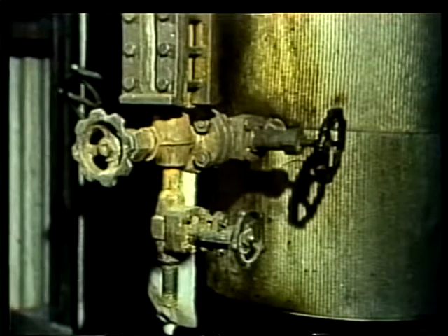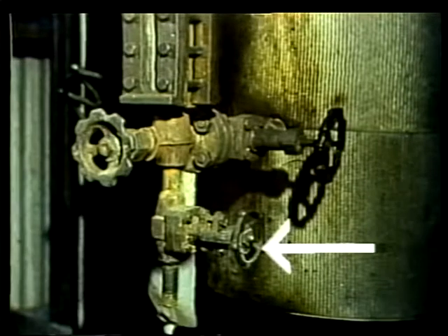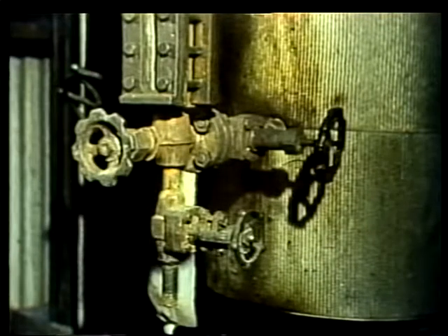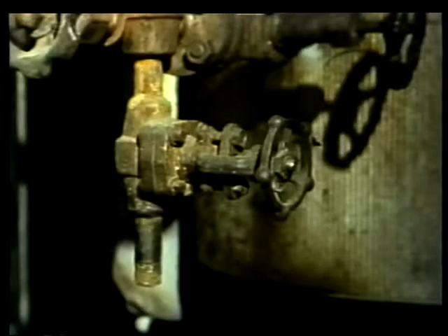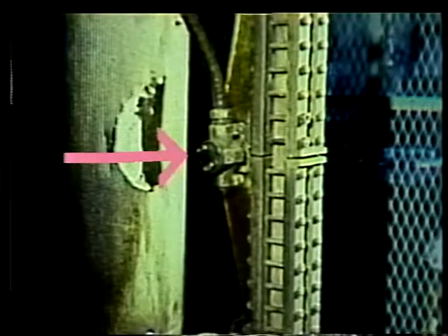Another feature on a flat glass gauge is the drain valve. It is attached to the bottom of the gauge and serves the same purpose as the petcock that is attached to the bottom of a tubular glass gauge. Both are used to drain the gauge when the rest of the plant is in normal operation. Some flat glass gauges have illuminators. That's because flat glass gauges are difficult to read if lighting is poor or the fluid is clear.